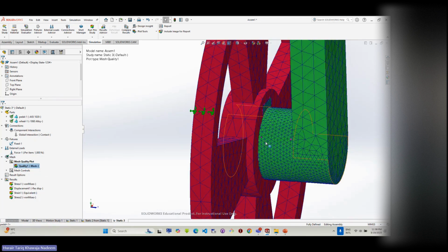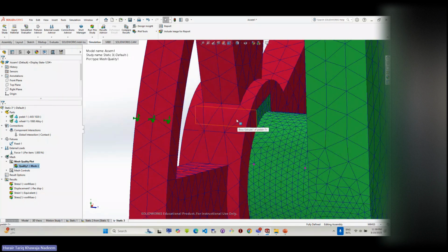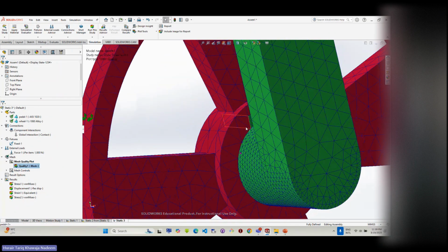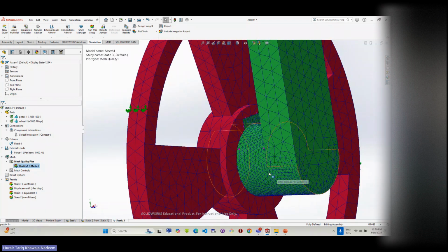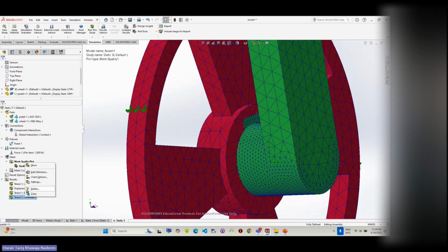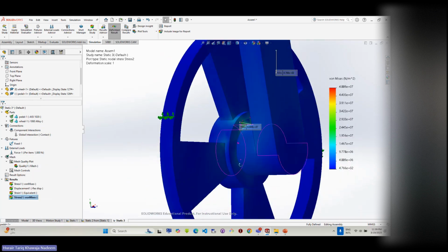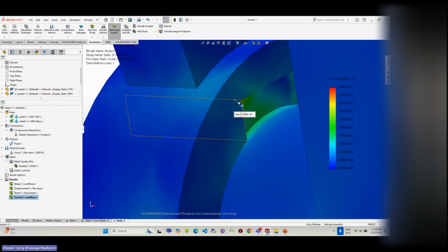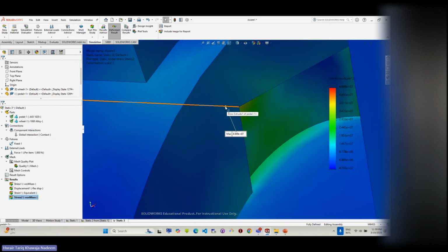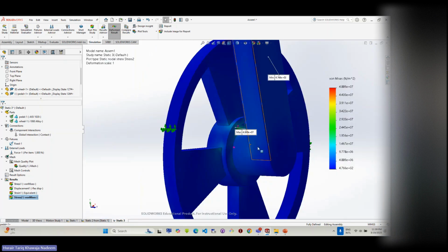Look at this. Over here, we have got a fine mesh, and over here, we have got a coarse mesh. But you can have fine mesh on that other side as well, okay? But on this side, because I selected the whole surface, I got a finer mesh, and finer mesh means better result, better accuracy, okay? So you can have this finer mesh, and then you can show the result, okay? And then you will see some other value. Look, the red is gone actually. It's somewhere now on the inside, okay? So it was over here before, now it's gone over here. And the value is also changed. We did not notice it, but definitely the value is going to be a little bit different from before, okay? So this is how you analyze this.